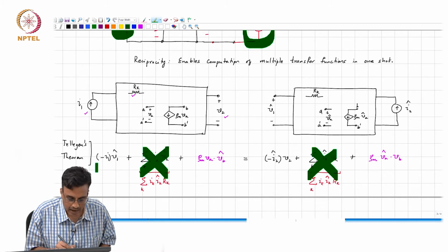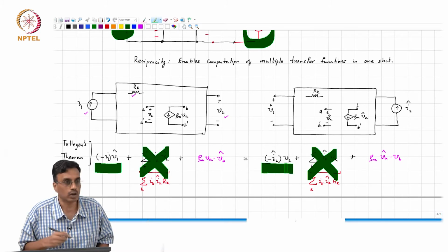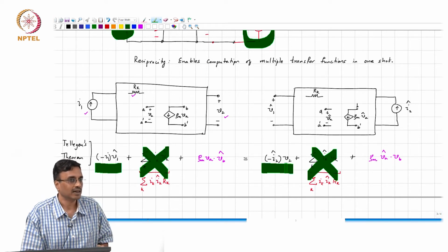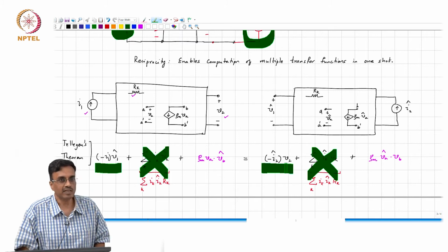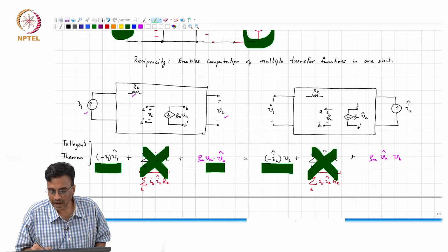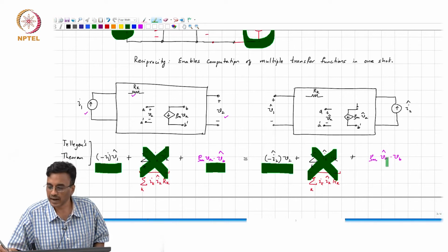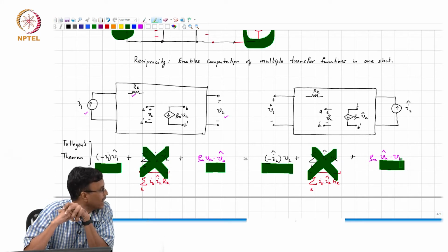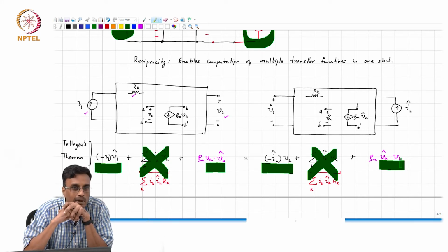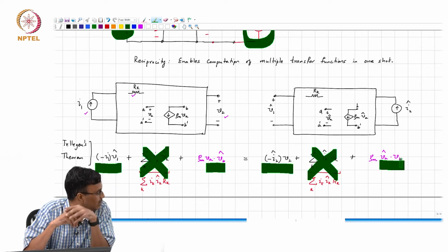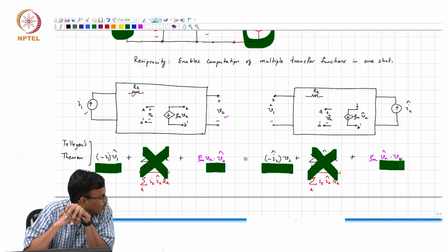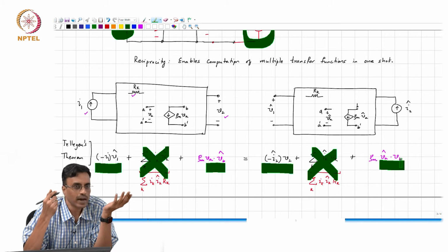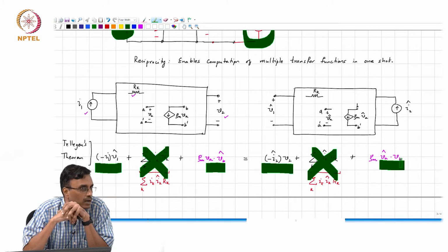And we would be able to get our desired relationship between the port voltages and currents, except that there is this little irritant, which is Va times Vb hat on this side, and this is Va hat times Vb. Are these two the same? I mean, can we move the hat from A to B and then be happy? I mean, are those two equivalent? The quantities in magenta, are they equal? There is no reason why they should be.